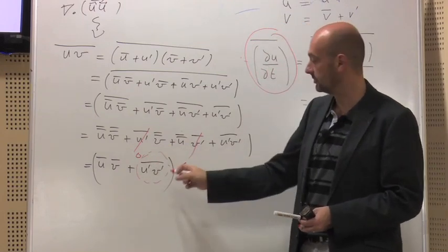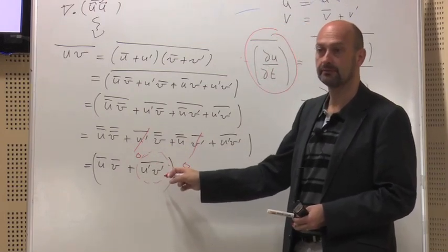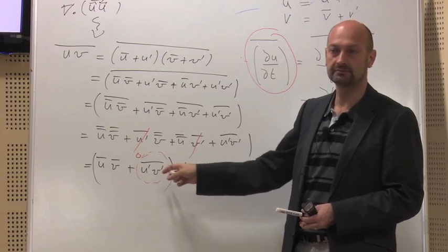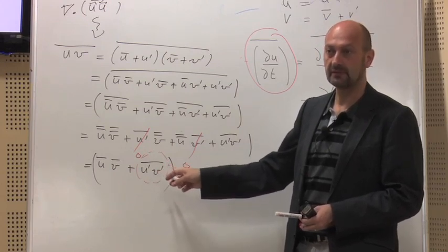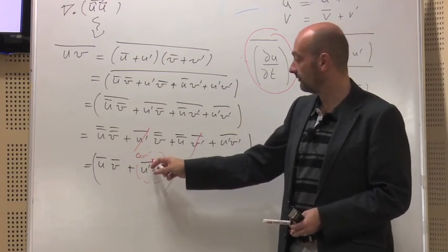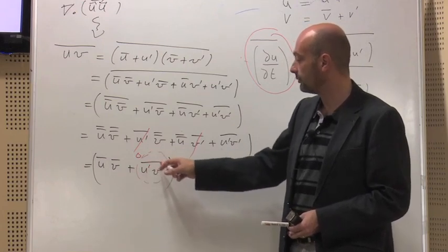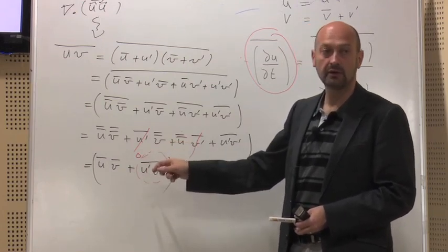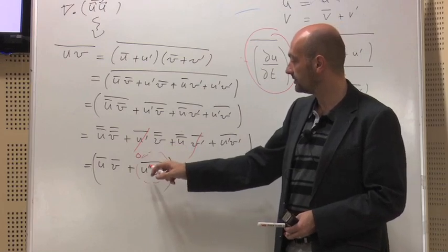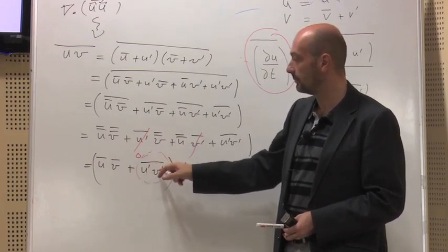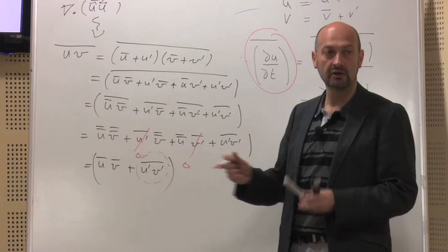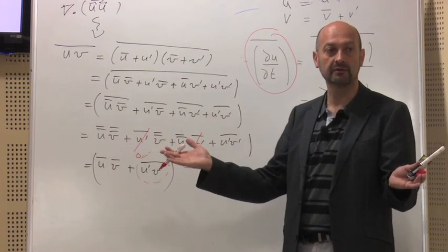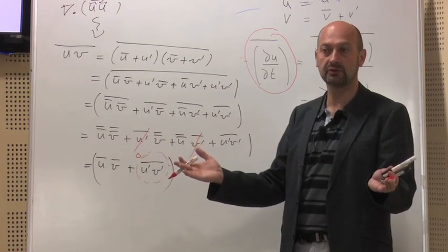is generally non-zero. Do you know when it is 0? Yeah, exactly. So for this average u prime v prime bar to be 0, you must have two variables, u prime and v prime, stochastic variables, which are completely independent. So there's no correlation between those two.